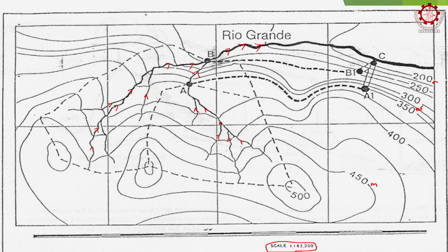So, now when you look at it, because we know for hydropower, I will come to this formula later, but for your benefit I will mention the power, we will discuss this later on. Power developed from a hydropower plant is equal to efficiency into Q rho G H. Rho and G we know, rho is density, G is gravitational constant, we are familiar with. Q is the flow rate, H is the height difference, or what you call the head, right.